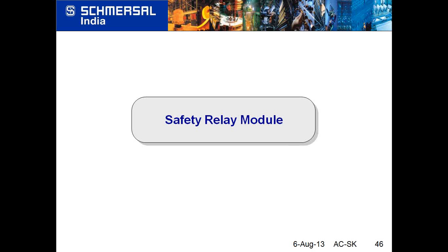And the most important role a safety relay plays in an automated control system for safety is the diagnostic coverage. So a safety relay builds intelligence into the system. Suppose you use an emergency stop device in a system without a safety relay and directly wired to, say, the contactor of the motor or the drive of the motor.